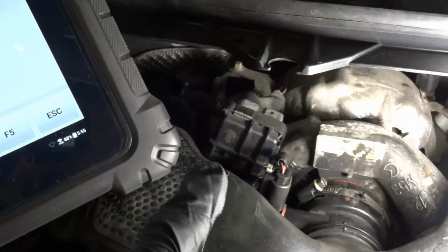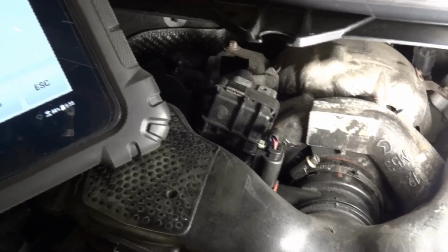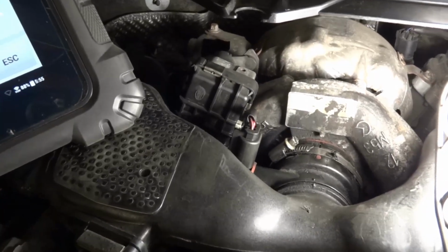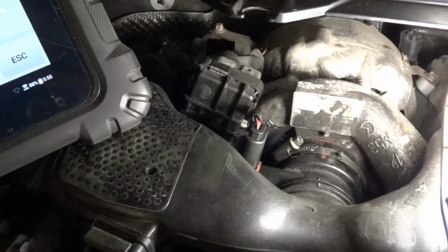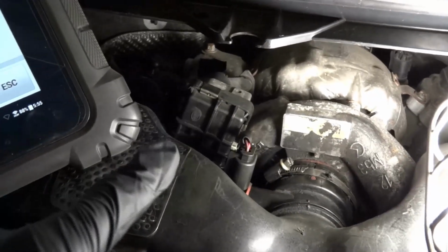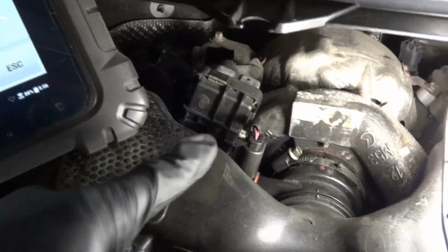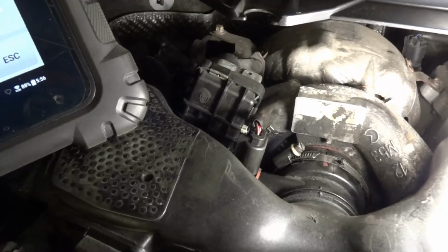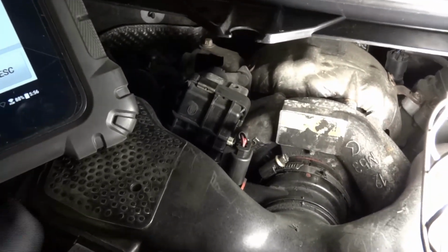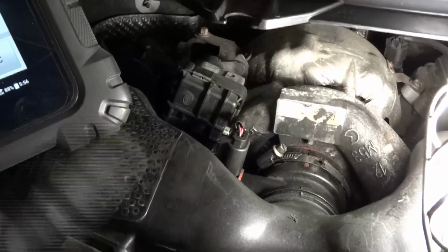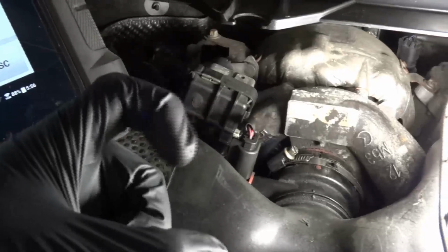I think I might have a used actuator here laying around in the shop. I did replace a turbocharger in a Sprinter not too long ago. The turbocharger was leaking and I kept the old turbocharger. The actuator is still on it. Actually, what I can do is disconnect this actuator and bring the old one I have, and connect it. We're gonna do the same test. You will see that when you actuate that one, it doesn't make the clicking sound.